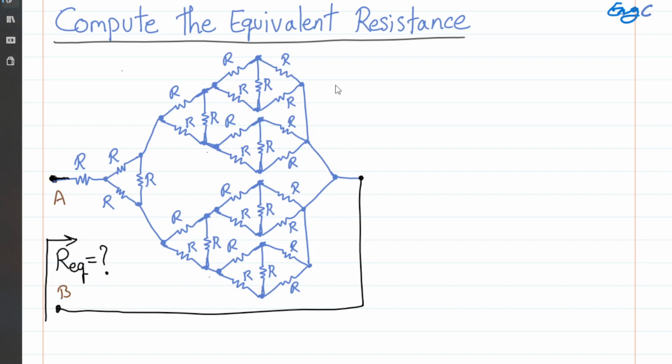Computing the equivalent resistance is illustrated in this example using an intuitive shortcut. In a brute force approach, when you want to find the equivalent resistance as seen from the port AB, you would just go ahead and simplify the circuit. Especially in this case, with these triangular structures, you would convert them to star format so that you would be able to simplify them. But we can intuitively use a feature in the circuit due to its inherent symmetry.